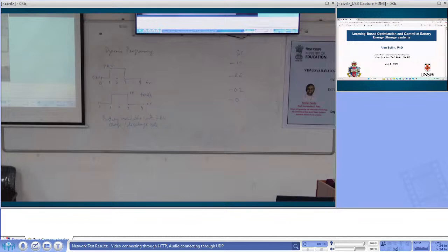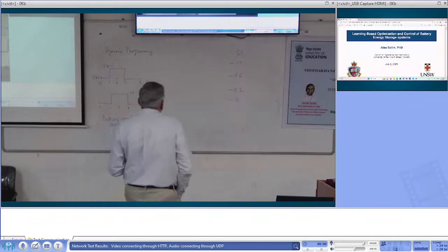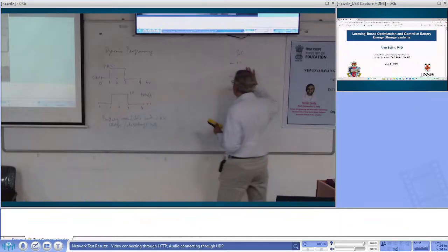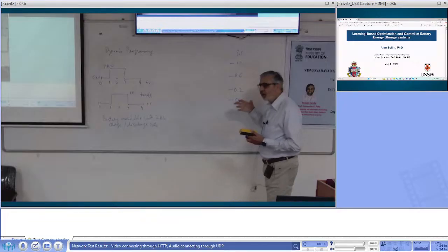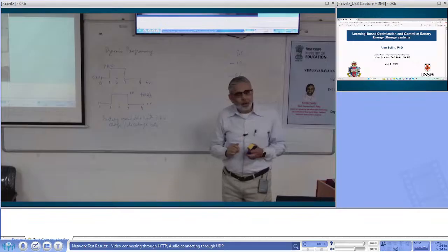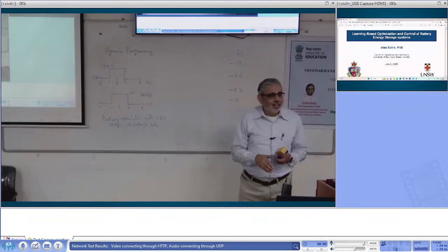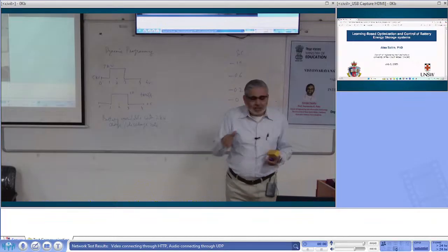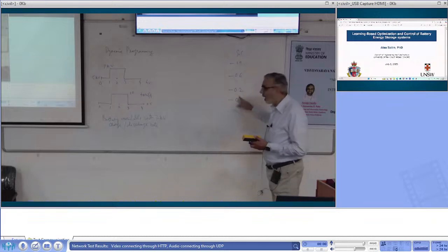Correct. So how do we tell the algorithm that? That's what I am asking. Using a relational operator between SOC and battery charge, power. So we need to give the operating points about the charging, depth of discharge. Yes. The highest charging point, that is 80% to 20%. The limits should be between that only. 100%. We will do that, okay? So this one is just a number, right? We can have 0.8 also, not a problem. But how do we tell the optimization program not to end up here at the end of 4 hours?